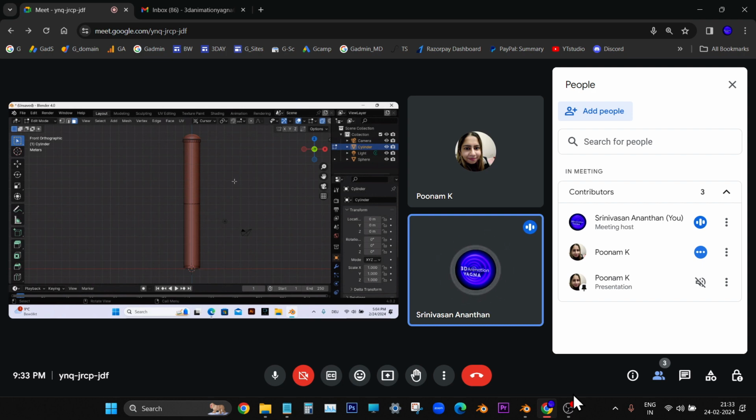Now we are going to add two horizontal loop cuts. Take your cursor to the cylindrical post geometry. Everything in Blender is a contextual menu, so keep your cursor on the object, the cylindrical post object. I'm calling it post, cylindrical post or cylinder, like that.